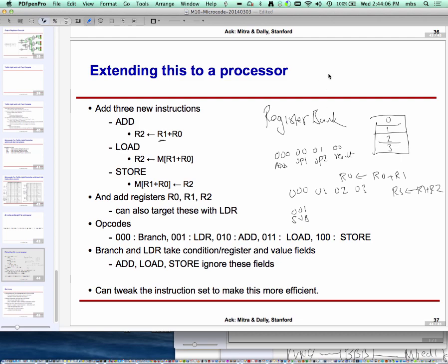There will also be instructions like load and store. What they do is they take the data from your registers and put them into the main memory of the computer, the big DRAM, or vice versa. Take something from the DRAM and move it into one of the registers. Why do you think we don't do arithmetic directly on contents of the memory? Like I showed how I can do addition on 2 registers and put the output into another register. Why not take contents from the main memory or DRAM, add them up, and put it back in the main memory?